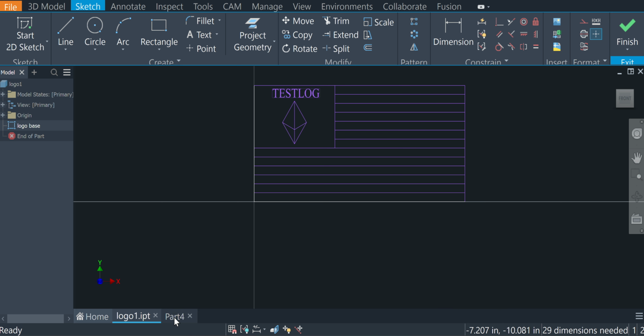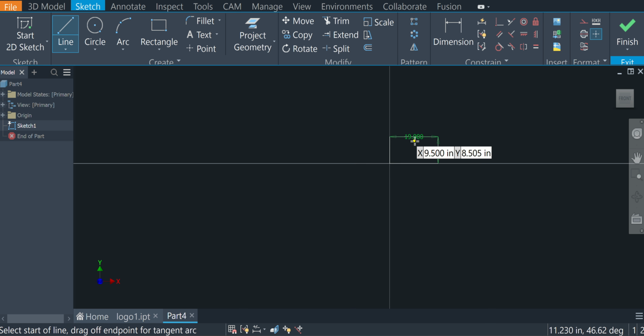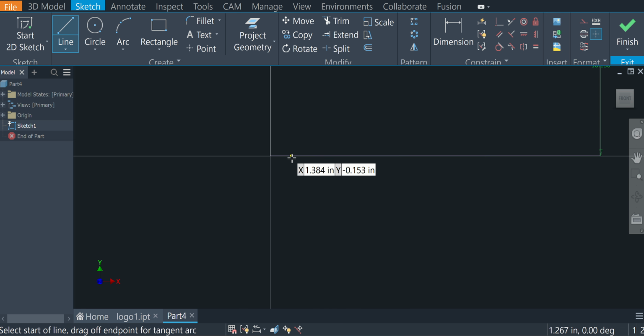So I'm going to go back to this and show you guys some more of the things that I did. Knowing what the dimension is, if you hover over the corner right here, each line, with the dimensions that I put on here, is 5/32, it's 25/32. So I want X to stay 0, and I want to move up on my Y. This is the X axis and this is the Y axis.